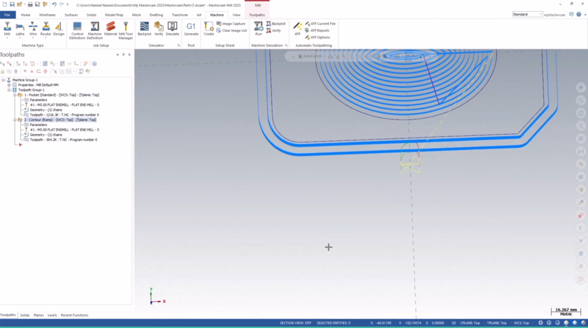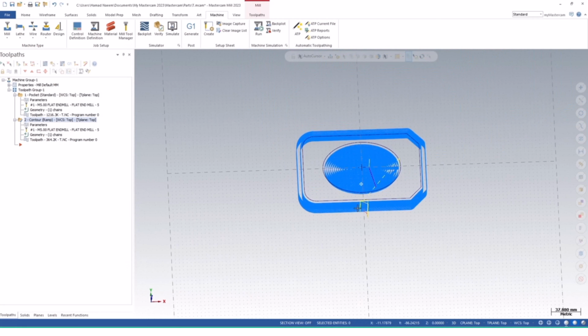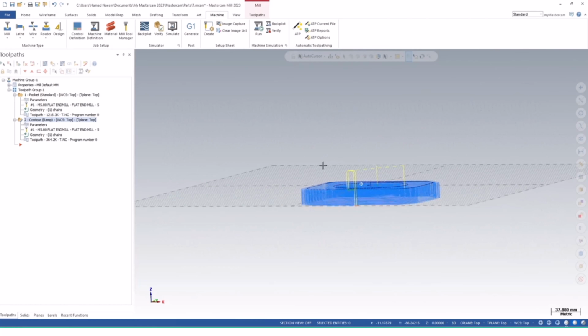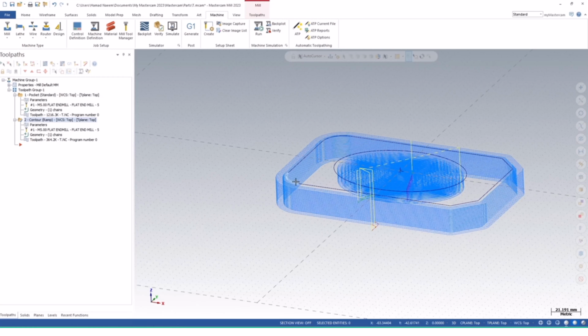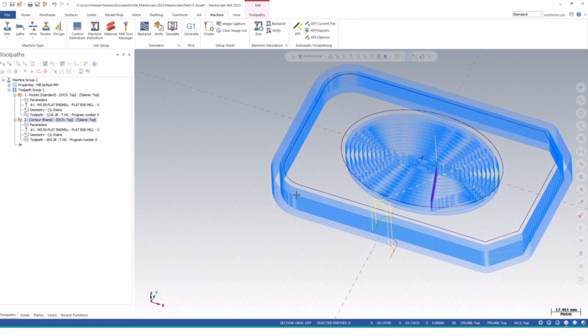So in this video, we have discussed how to define the depth or milling depth cuts, milling lead in and lead out, and we have discussed the multi-passes and why we use the multi-passes, because we want to perform multi-passes operation on a forging or a casting piece.